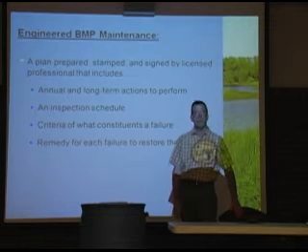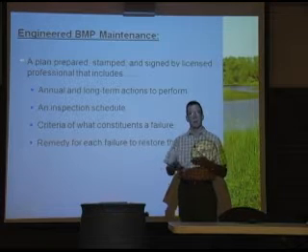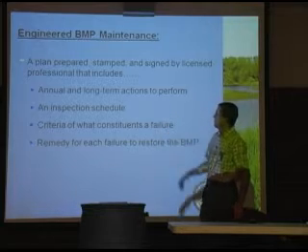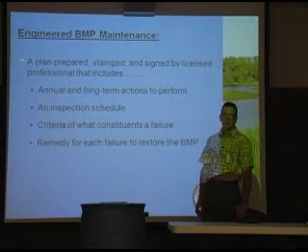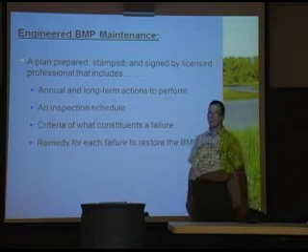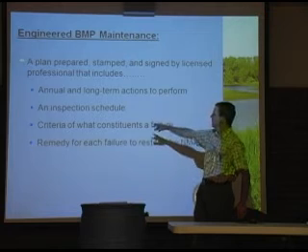from your licensed professional. You need a maintenance plan stamp. We wouldn't know how to maintain them because there's, like I said, thousands of possibilities. So they've got to tell you what you need to do to maintain it, short-term and long-term. They've got to tell you what to inspect and the schedule to inspect. And then when you do inspect it, what are you looking for?